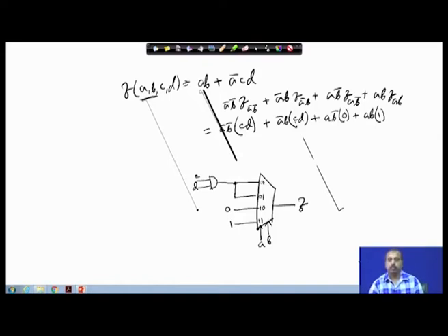So, without going into the truth table, you can use this generalized Shannon expansion to go to the multiplexer based realization of the circuit. As the number of select inputs increases, the decomposition becomes a bit complex and lengthy. So, decomposition has to be for all the input combinations of the select variables.